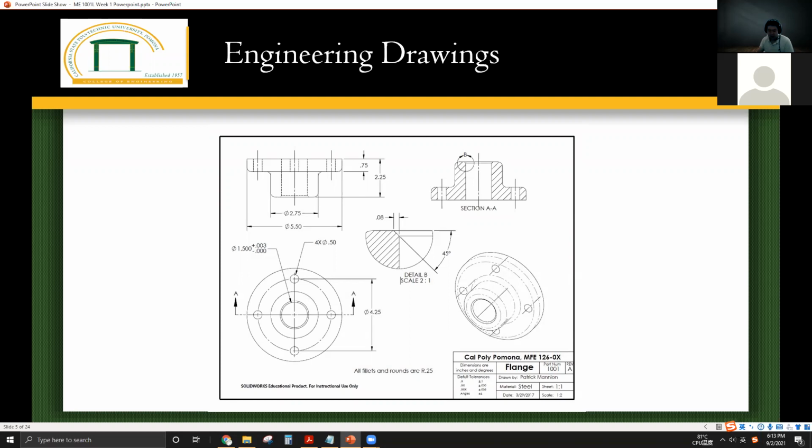Yep, I see the right answer. Yes, so you're going to fall into the third line because it has 3 decimal places, 500. So it goes into .xxx, and its tolerance reads plus minus 5 thou. So if it doesn't have its own tolerance, this part can go to 1.505 or 1.495.